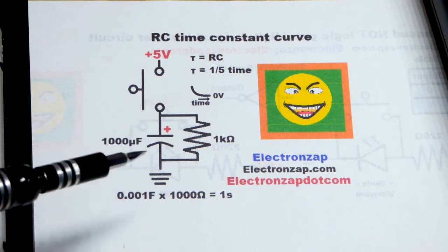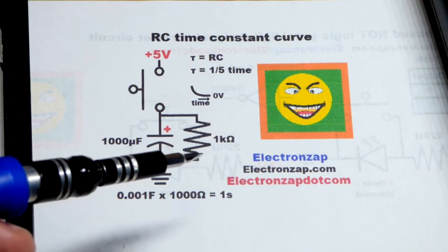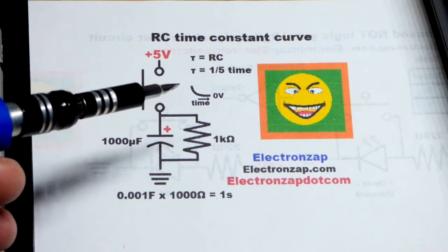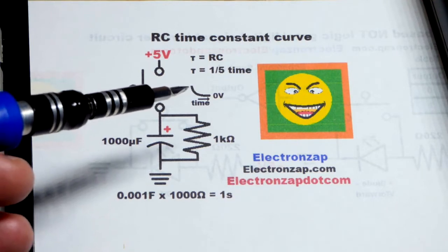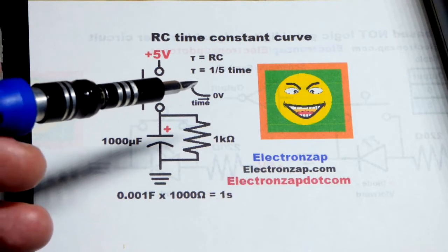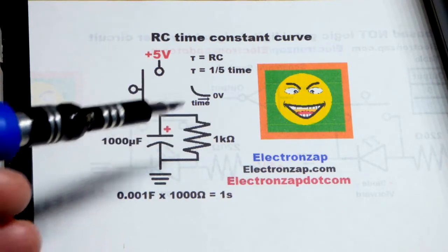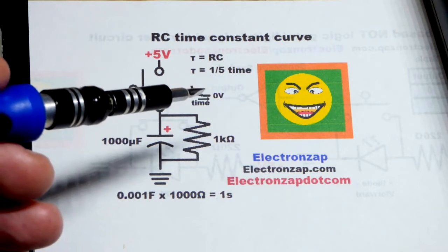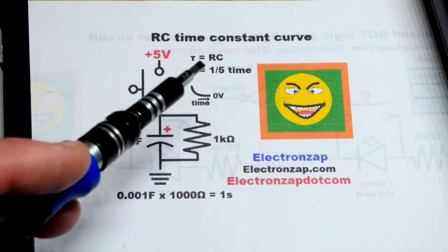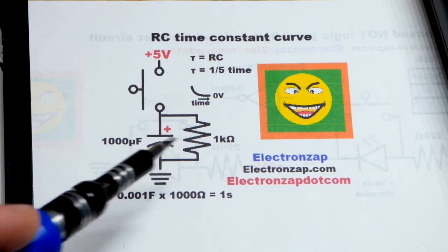And then when I released the switch, the LED stayed really well lit for a brief period of time, but it quickly dropped and faded to off. So if we were looking at the curve, which we're going to do in this video with the oscilloscope, the voltage would be holding as long as I had the switch pressed. As soon as I release, it rapidly drops as the capacitor is discharging through the resistance there and slowly fades down to zero.